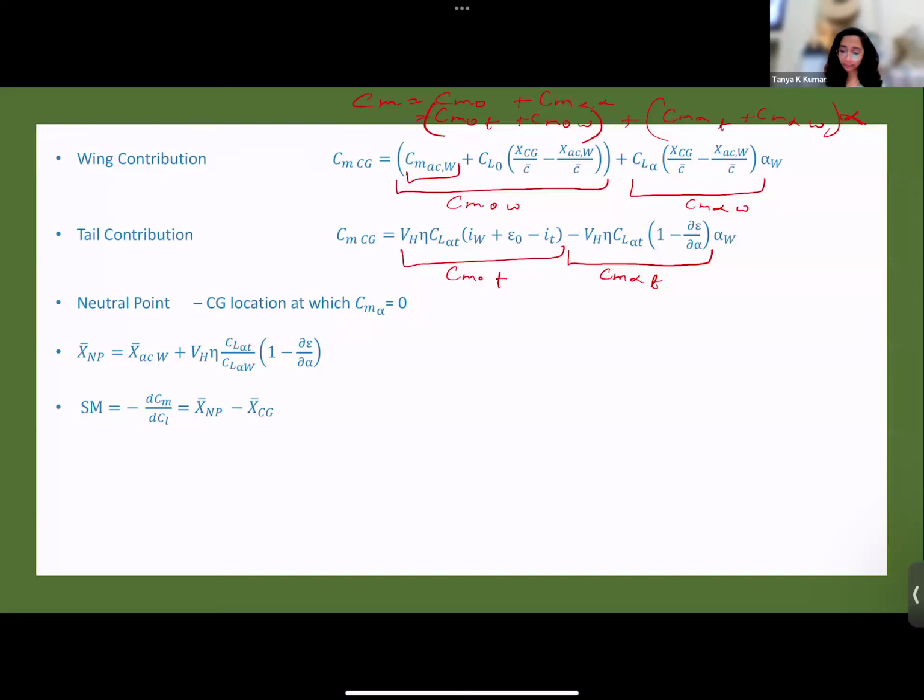So this term is for the cambered airfoil. For the cambered airfoil, is it positive or negative? It will be negative. Correct. For a symmetric airfoil, it will be 0. For a cambered airfoil, it will be negative. And for a reflexed airfoil, it will be positive. So your CMAC came because you were transferring your forces from your CP to your AC, so it comes with a moment. So that is your CMAC: 0 for symmetric, negative for cambered, and positive for reflex.